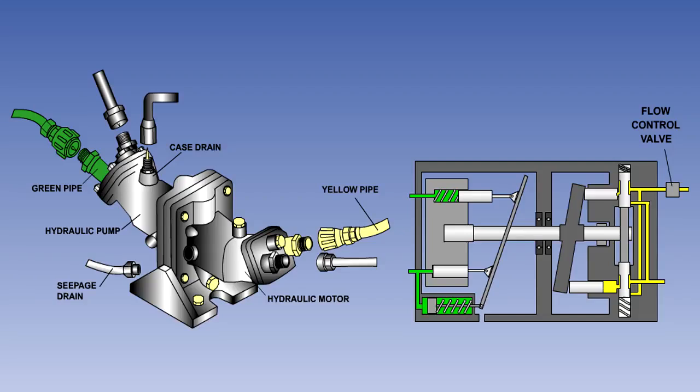In the setup shown here, the hydraulic motor is driven from the yellow system and the pump is pressurizing the green system. So this particular power transfer unit, PTU, would operate in the event of a main pump failure in the green system. Note that there is no exchange of fluid, so the two systems remain separate.